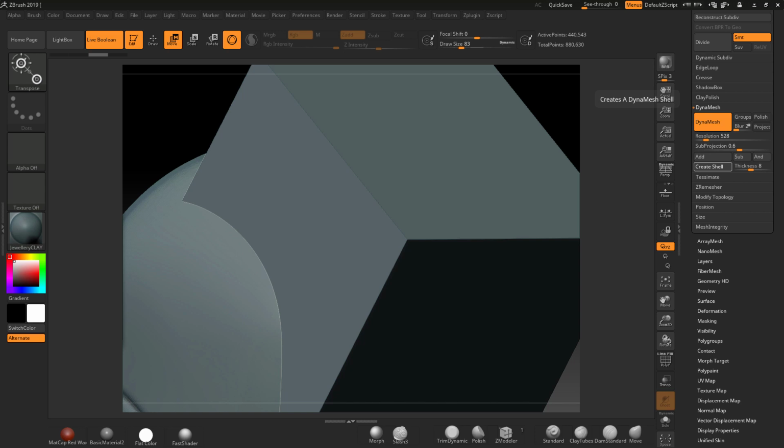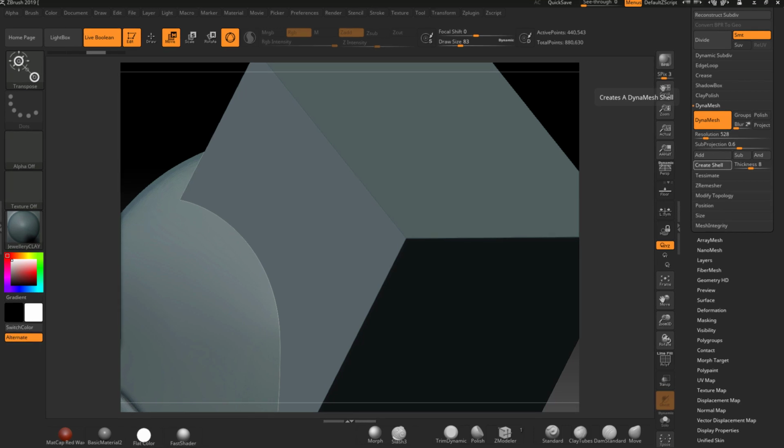Now it'll create a shell on the inside that will be all over the mask at 2 millimeters, so you'll have a consistent size. From that point we can use the original mask, and we can actually boolean away the parts we don't need. Just as a little tip here, it might be a good idea to work with another mesh first to get the thickness value, a lower resolution piece of geometry, and then your actual shell creation will be quicker. You'll get the right size, and then you can apply it then. Just a little tip.